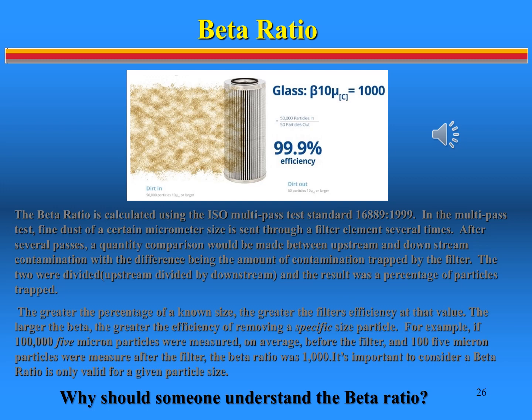Fortunately, now a test procedure called multi-pass testing or beta ratio testing is a universally accepted test method that yields readily comparable test results. It was introduced with the object of giving both filter manufacturer and user an accurate and representative comparison amongst filter media.